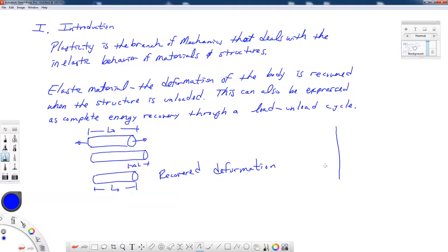So if we have a stress-strain curve, and we have elastic material behavior, and it can even be nonlinear elastic, that's okay. It gets a little bit curvy right here, where at this point, if we release this, and we get back here, trying to show this following the same path to zero stress and strain, we do not have any area contained inside of that curve that I just drew.